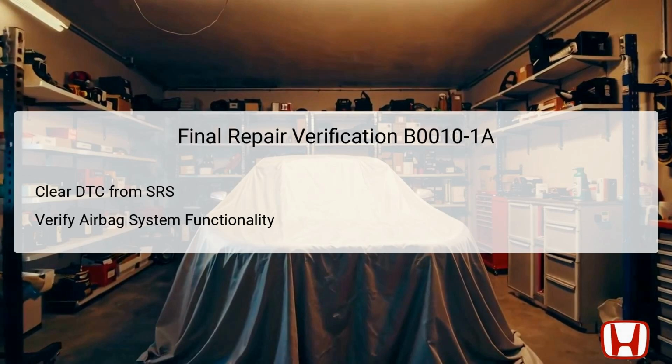Once the DTC is cleared, it's prudent to conduct a functional test of the airbag system to ensure it operates as intended. This involves monitoring the airbag warning light and ensuring it turns off appropriately during system checks. During this time, the technician should confirm the deployment of the airbag signals via the diagnostic tool.